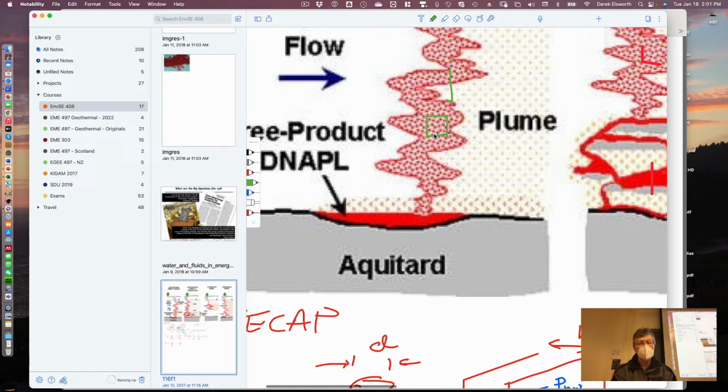And so that's kind of the approach that we'll take here. Instead of trying to figure out exactly what the behavior is by using lots of little capillary tubes, what we could do is take an experiment, take a block of soil, put it in some kind of apparatus, push some fluids into it, measure the pressures of those fluids in aggregate, and then use that to say something about what the height rise would be in this system. That's what we were attempting to do.